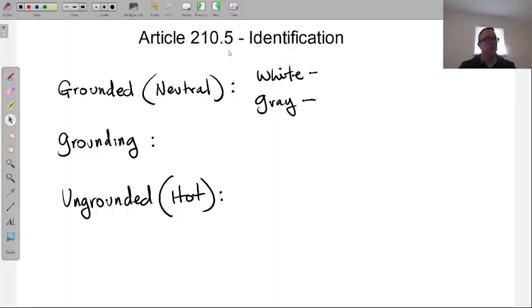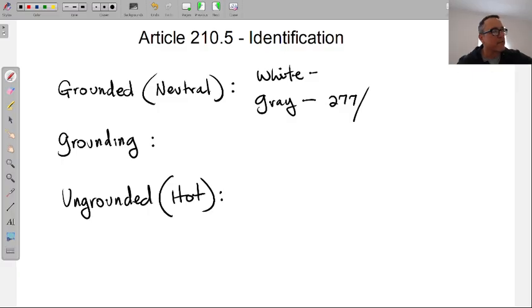Very good. It's for the 277. Anytime we write them, yes, it's for the 277 circuits in the high voltage world. Never for the 480 volt circuits, because those are not going to be using a neutral. But we always represent both voltages of the system. We always call it a 277/480 volt system. So it's the single phase of the 480.